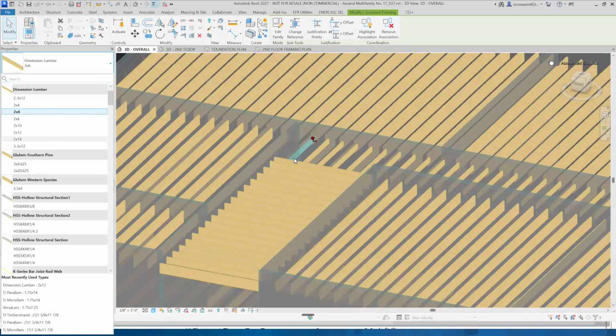Now, if we search to the four corners of the earth and can't find it, you'll just get a little pop up that says, hey, we couldn't find it. And we temporarily put that in a warning state because we weren't able to toggle your size. But that's pretty rare because it's a very robust retrieval process. So you absolutely can load new sections on the fly automatically. The same with steel design. You can start with just one steel section and you can tell ENERCALC that you need a 30 by 90 or whatever. And when you save and close, it's going to get loaded on the fly as long as we can traverse your loadable content.